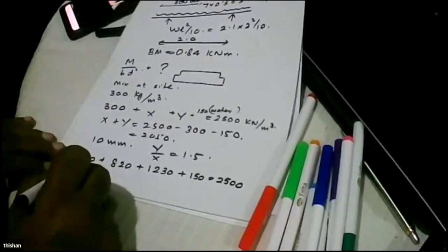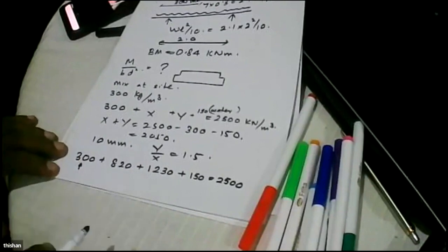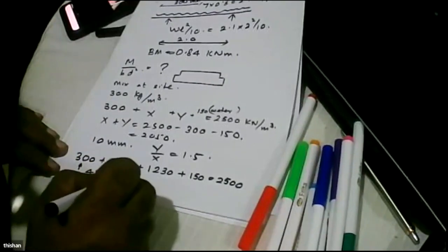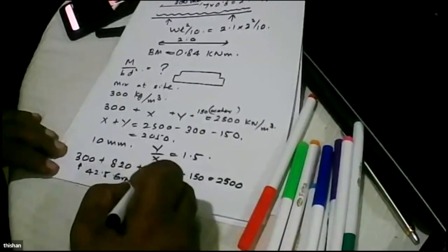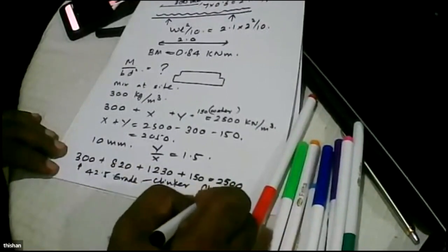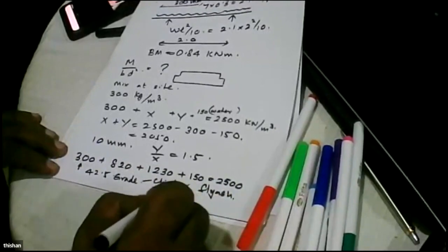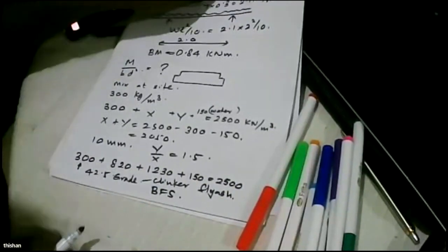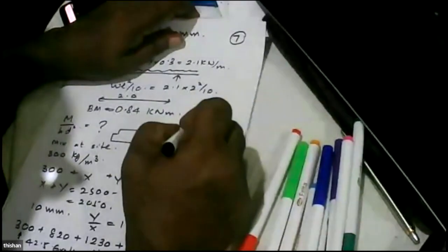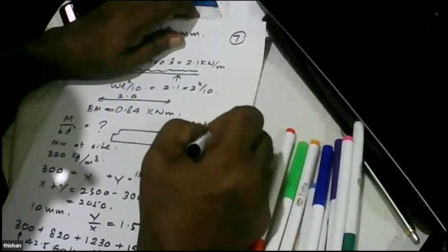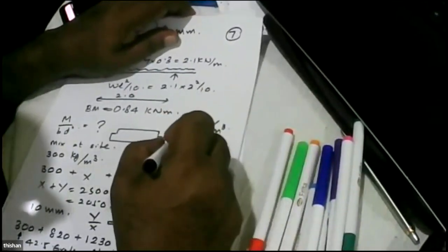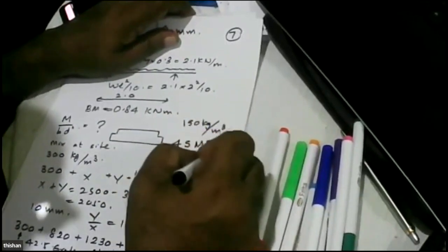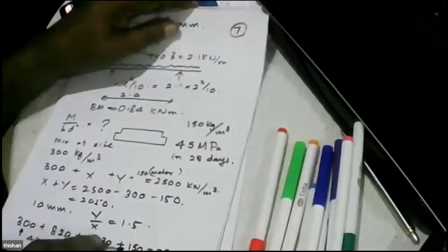And if you use good quality cement, meeting 42.5 grade, that might contain clinker, fly ash, blast furnace slag, any of these things, you will find that because we are using 150 kilograms per meter cube of water, this can reach about 45 megapascal in 28 days when we compact it well into the shutter.